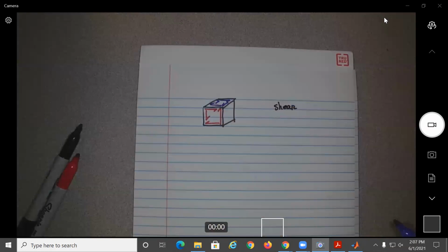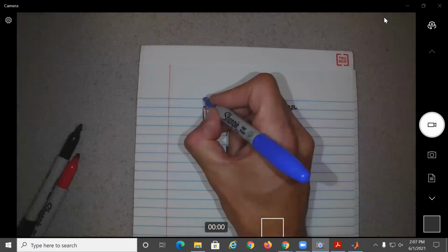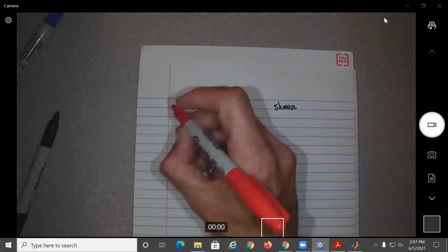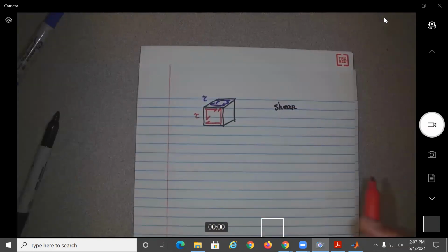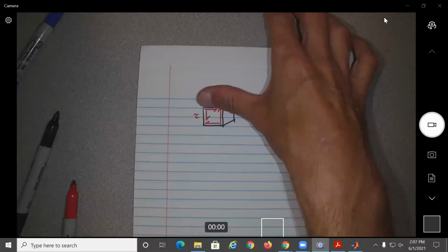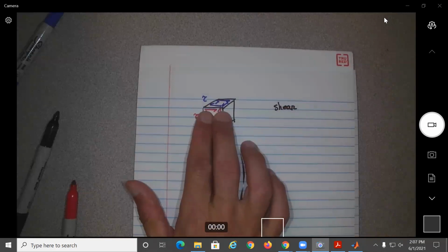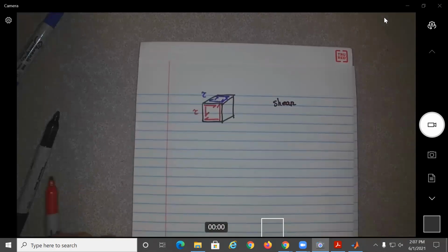Basically, the only thing I'm trying to show is that the value of the shear, the tau blue and the tau red, should be the same one. So you should be able to calculate the tau looking at this face, which is what we did the first time, or by looking at the top face, which is what we did the second time. I hope that makes sense. So we did calculate the shear at points A and B. At point A, we found that it's 0 due to VZ only.